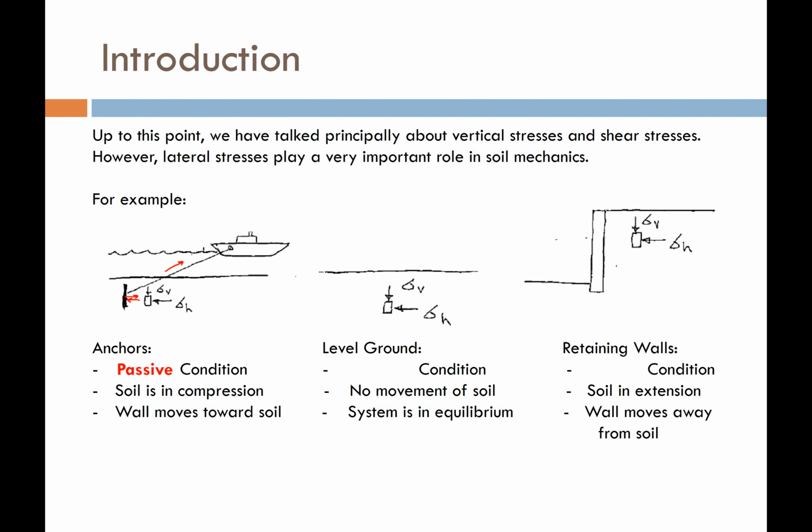We have another condition where here in the middle, if there's no loading going on at all, we have no induced stresses, we have just the soil all by itself sitting under its geostatic stresses, the vertical and the horizontal, and everything is in equilibrium. We call this an at-rest condition. So the lateral earth pressures that the soil would be feeling in this state are the at-rest lateral earth pressures.